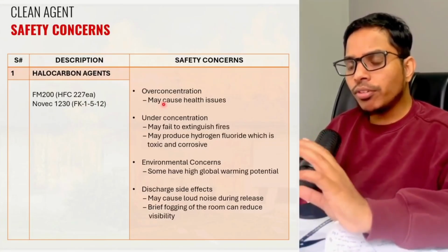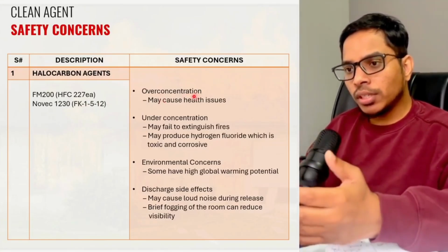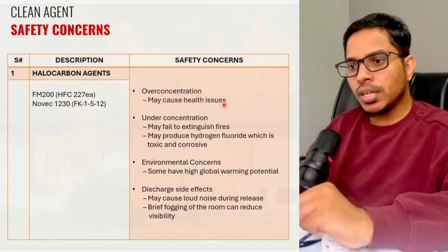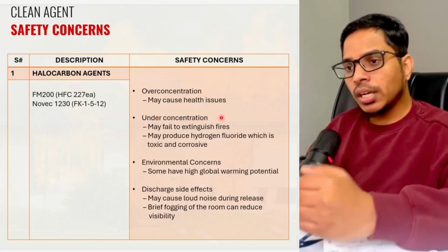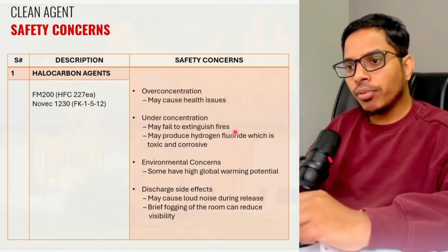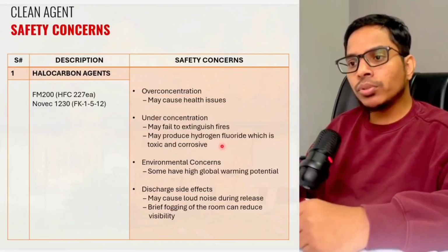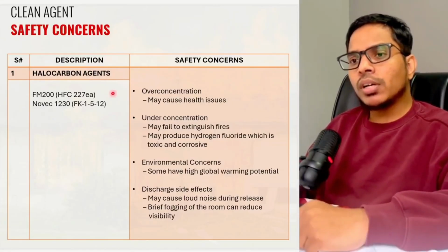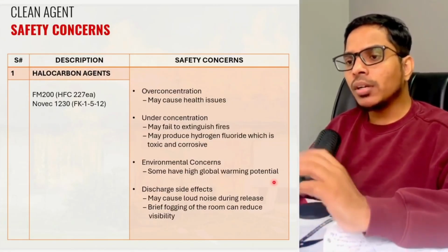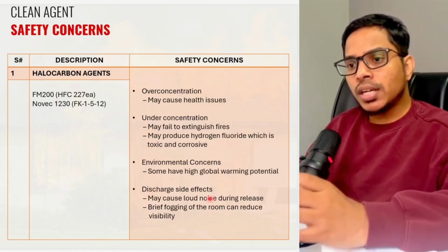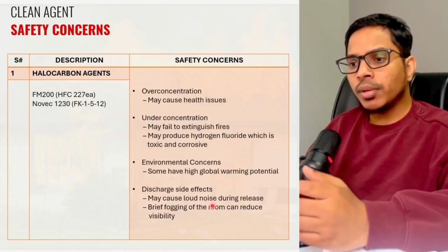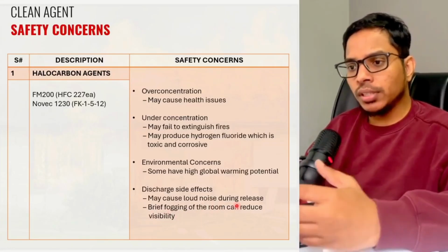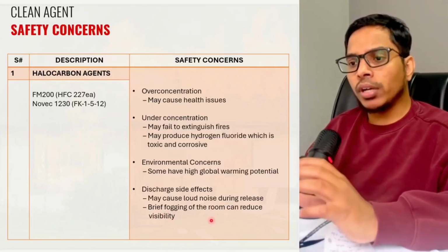For now, please note, if we select the design concentration quite high than required, then they may cause health issues during the discharge, and if we consider the concentration less than the requirement, then they may fail to extinguish fires, and they may produce hydrogen fluoride, which is toxic and corrosive. Apart from that, some of the clean agents have high global warming potential, and the discharge side effects will be like they may cause loud noise during release. Obviously, this happens because of the large pressures in the cylinder,